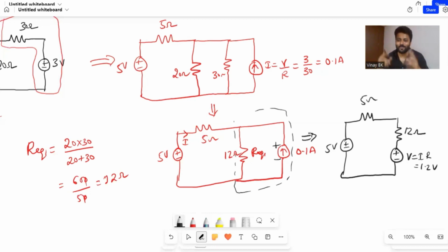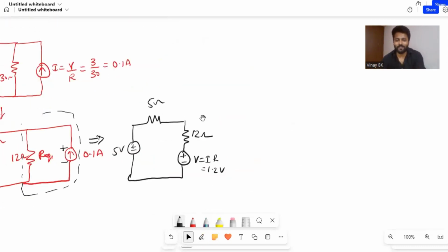So now we have two voltage sources in series, so you can do addition or subtraction of these voltage sources. Now I will rewrite this circuit. So now 5 volts, minus plus, see now I am tracing here. If it comes on the upper side, minus plus 5 volts, then 5 plus 12 are in series. R equivalent 2 is 5 plus 12, that is nothing but 17 ohm.